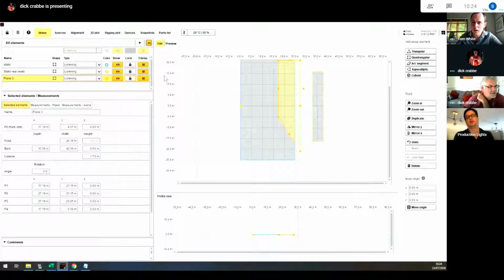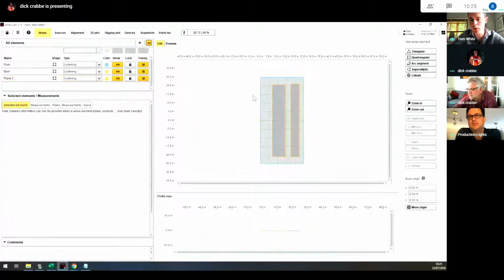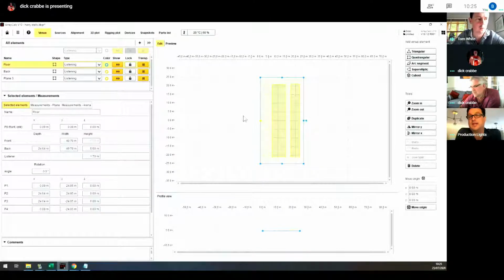Yeah, exactly. And Dick, I don't know if some people remember a few weeks ago when we were doing the stage layout, the markout in AutoCAD. When I type in something like 0,0, that's the same as this. It's just doing exactly what Dick had on the screen just then. So it's going X 0 and Y 0. You could in theory type in any measurement, and that's what it does. And I think AutoCAD a very, very long time ago was all like that. And Dom, I don't know if you agree, but yes, it was.